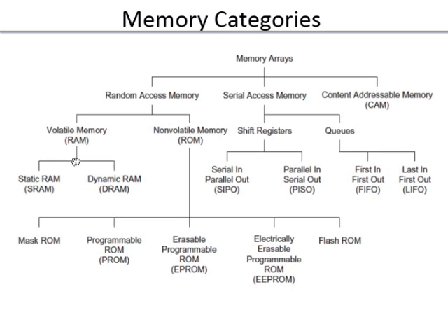And for the volatile memory, there are basically two classes: static memories and dynamic memories. Static memories are memories where information remains in the memory as long as power is there. Volatile static memory. You have to give power, but you don't have to do anything else. As long as power is connected, it maintains information. So that is a static memory. Whereas a dynamic memory is, even if you have power, it can leak away. So periodically you need to refresh.